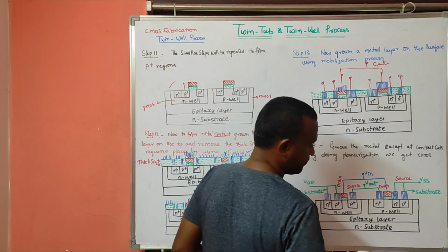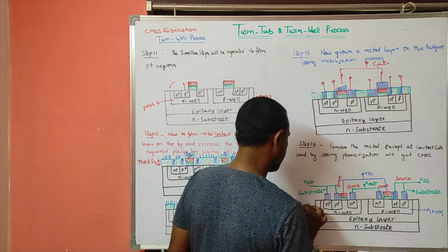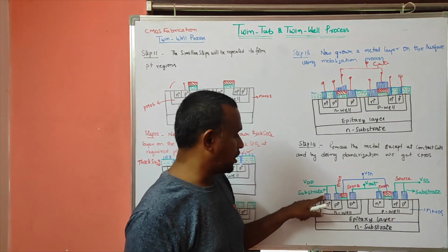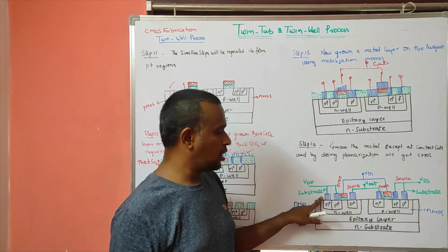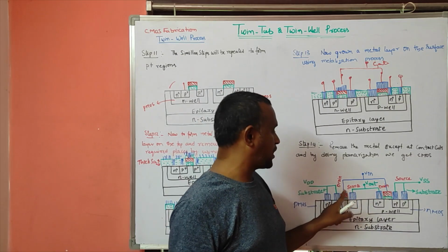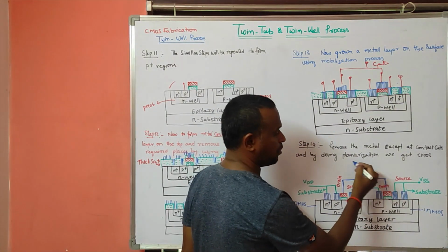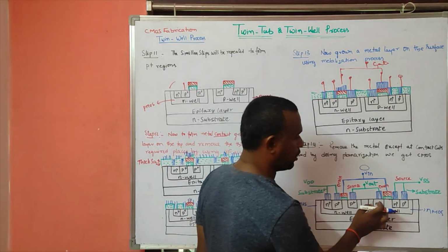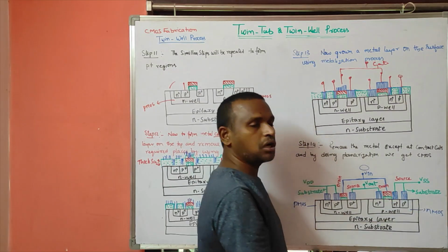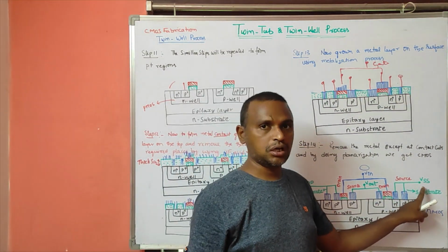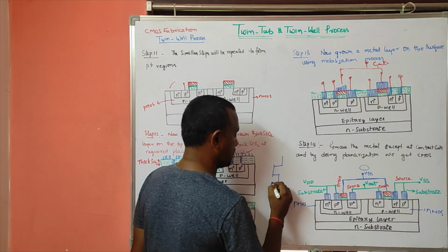So what is it? It is the NMOS, sorry, it is the PMOS, and this one is the NMOS. Okay, PMOS, here it is considered as the drain. Okay, drain, and this one as the substrate terminal, and at the same time here the two gates will be shorted. This gate of NMOS and PMOS will be shorted, and this will be applied as the input. Okay, next here we have the drain and source of this NMOS, and that is connected to the ground. The source of NMOS will be connected to the ground. The inverter circuit will be like this. The basic circuit of CMOS will be like this.